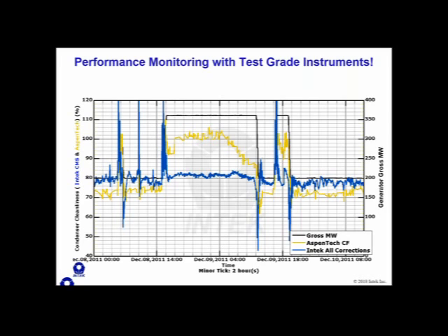We covered important techniques like using a no load time period to validate cooling water temperature instruments, those values. The importance of proper location for those measurement points as well. And I showed a cost-effective way to, well, what I believe is a cost-effective way to continuously measure cooling water flow. It's a parameter that's not often monitored.